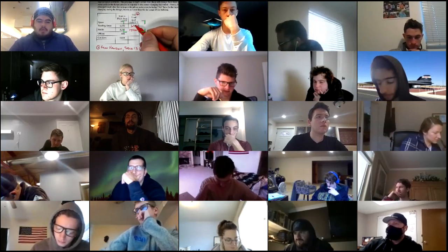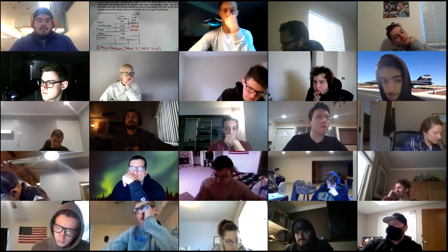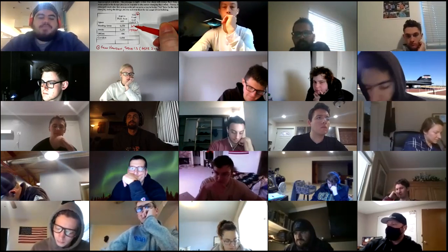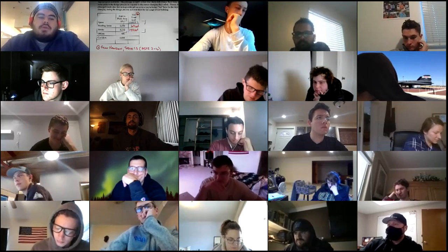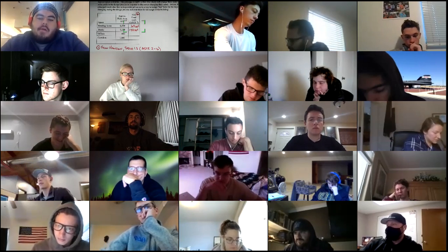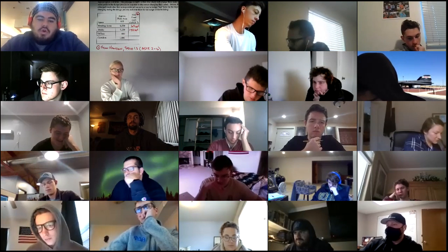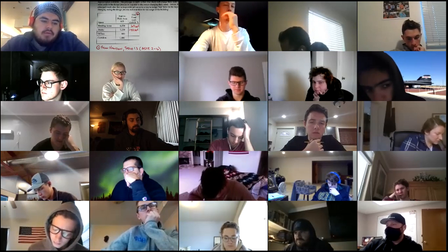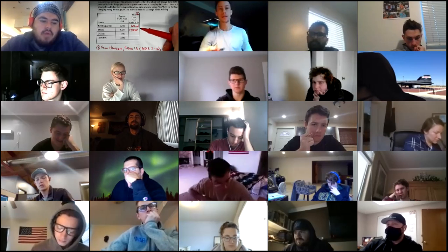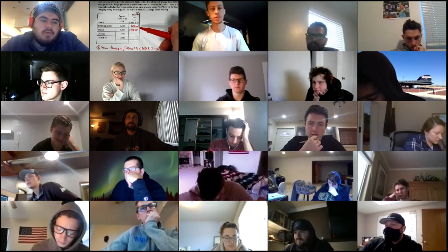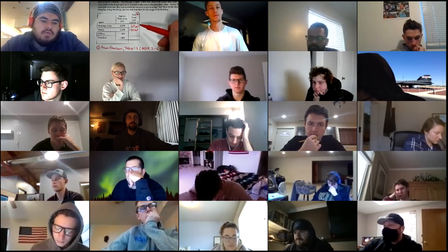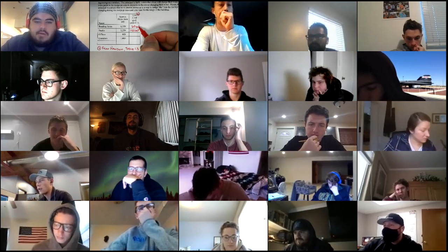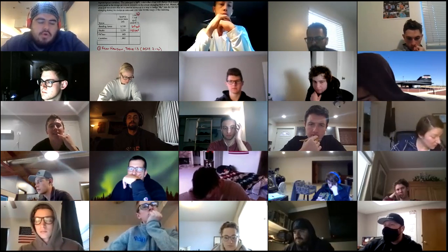So what happens here is, remember, we're sort of saying that we're just going to lump all these areas or these loads, whatever's causing them, into some sort of smeared out value. So 60 pounds per square foot is for reading areas. Well, reading areas are where you have tables and chairs and people, right? And the actual load that goes to the floor are a bunch of concentrated forces from the points of the legs of the chair and of the table, if you're standing, of your feet, but you're moving around, right? And what you do is you take all that load and you just smear it all out, right?